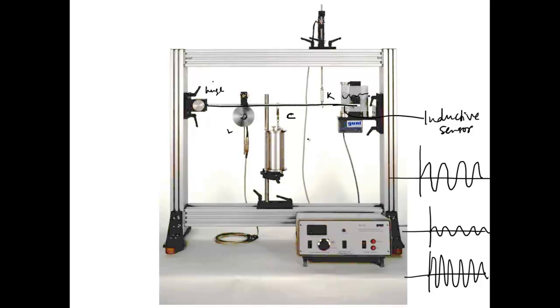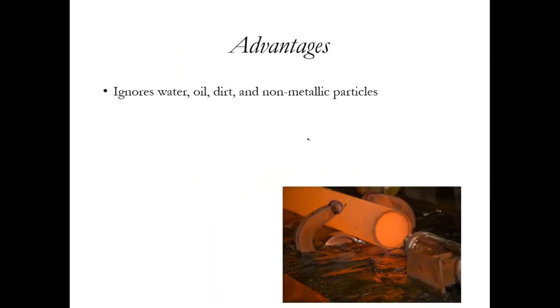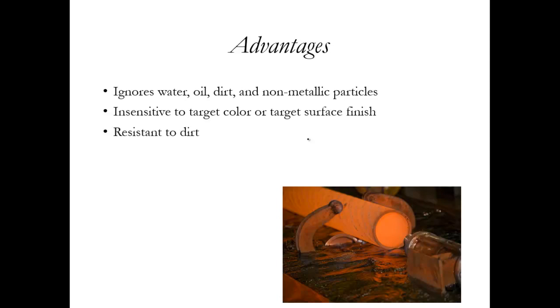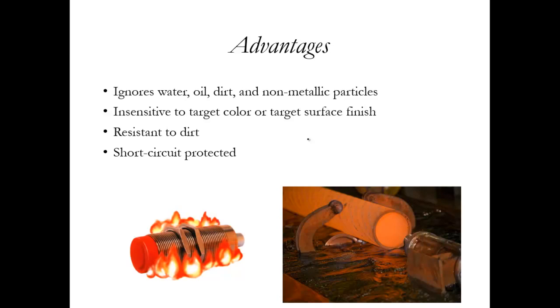I just wanted to give it some practical significance of inductors. Obviously the advantages are it ignores water, oil, dirt, and non-metallic particles. It is insensitive to target color or target surface finish. It's resistant to dirt, short circuit protected, and it withstands high shock and vibration environments. These are some of the good things about inductive sensors.